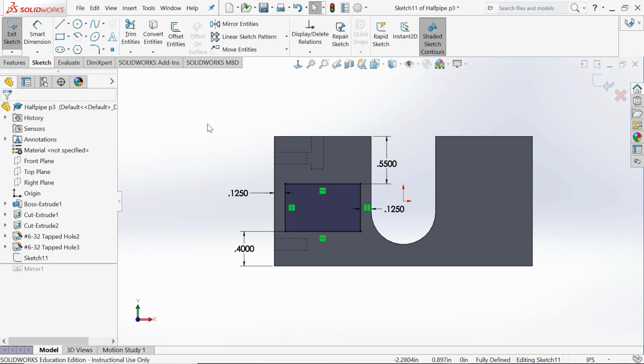Again, the bottom line to there. Yeah, I just pull it over to the side. You could do it from the point to the bottom, but since the two lines are forced to be parallel, it's better to dimension from the line to the line. If you have an option of dimensioning from line to line rather than from point to line or point to point, it'll always be superior. And I'll show you why later.